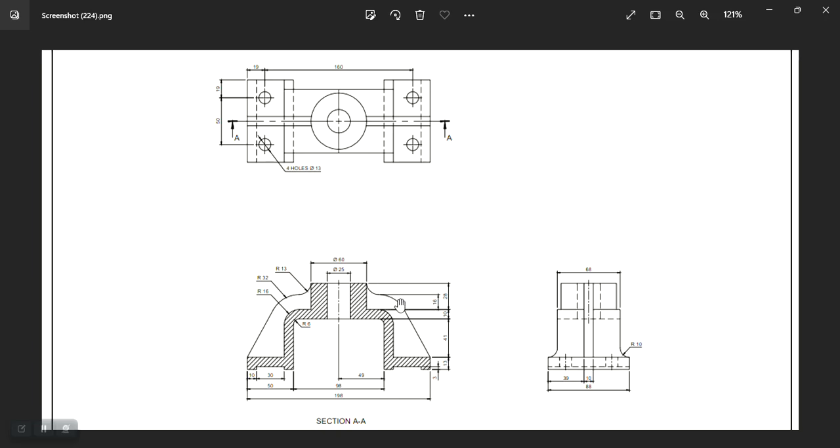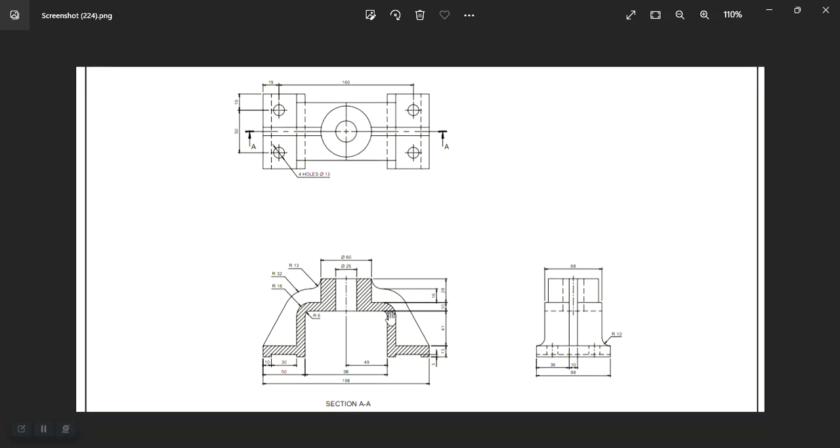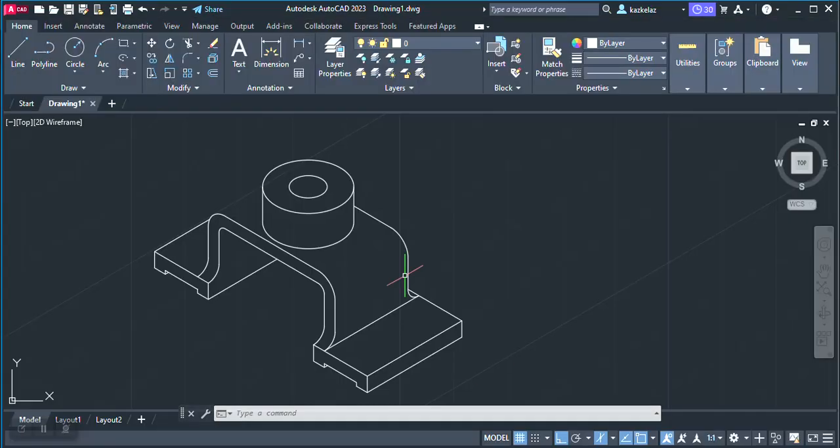I change my isoplane, select elliptical arc, then isocircle. It shares the same center with those arcs, so it's of radius 32. I'm going to move through an angle of 90 degrees like that. I know that it's actually not where I put it. I need to put it from the center. I need to go 5 to that side and 5 to that.